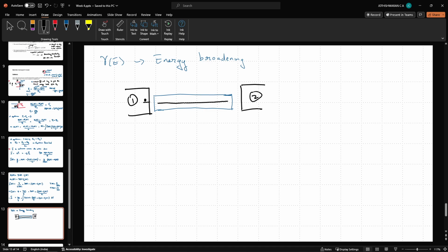This is kind of a muddled diagram, but kindly bear with me. There is another energy level over here. So an electron essentially transitions from this energy level to this energy level, and then after a certain time it will transition from this energy level to this energy level. So this is what we mean by charge conduction in a ballistic channel. Ballistic charge conduction is not actual translation of the electron. The transport of the electron is fundamentally quantum mechanical.